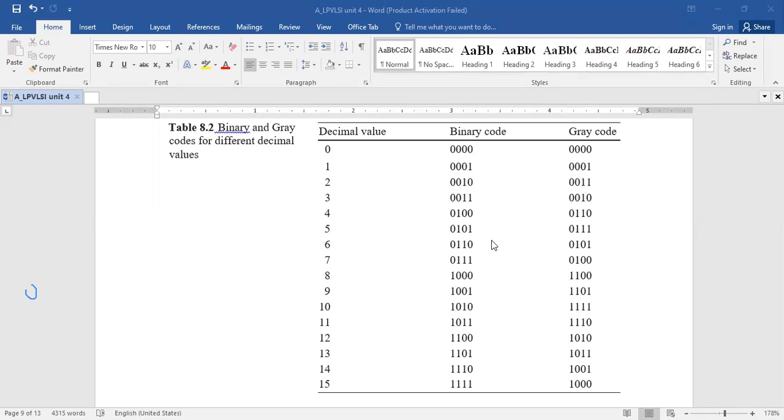And here one-to-one mapping is done. Whenever you're using this, just one bit transition is seen between two consecutive memory locations. Then the switching activity is only one here. Whereas here, if you consider, the switching activity is more. The same data is encoded in a code form and you're transmitting on the bus, so the switching activity is less. If the alpha is less, then the power dissipation is also less. By this, you can reduce the power dissipation.